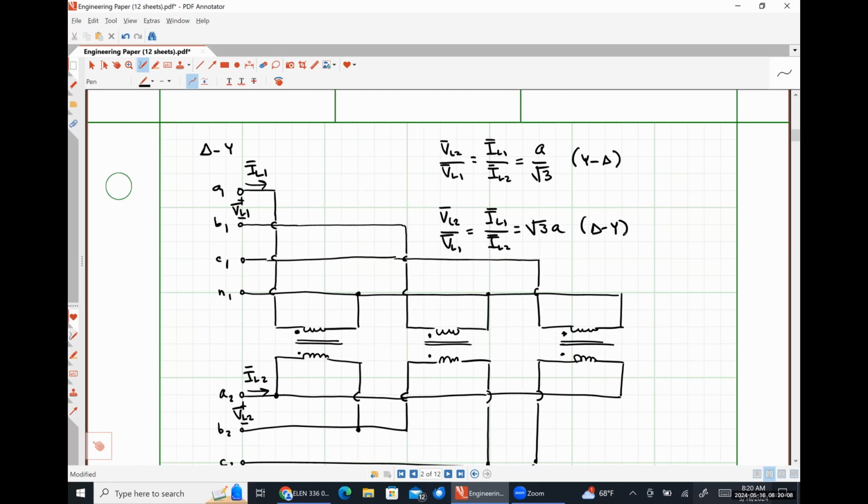By that, I mean, let's say that we purchase online a step down transformer, which means that we would be stepping down some high voltage to a lower voltage. If we literally connected our transformer in the opposite way, we would have a step up transformer. It's literally the exact same thing. We just apply one set of voltages on the low voltage side and take the high voltage terminals to give us that.